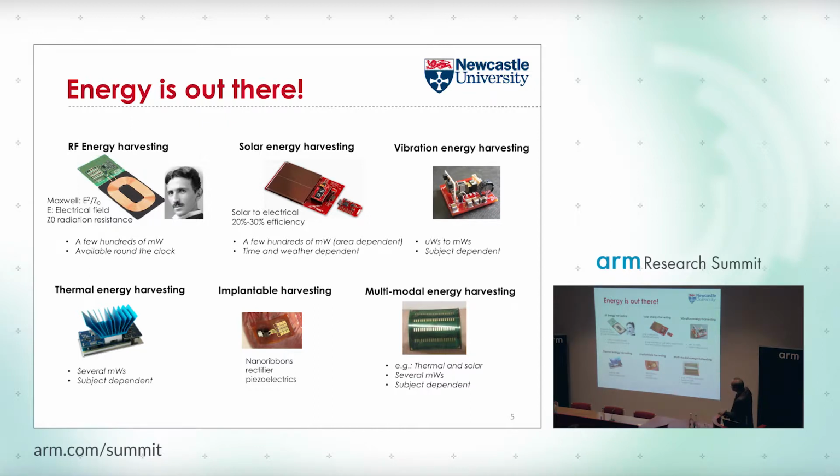Then we have some newer trends of thermal energy harvesting, or even implantable harvesting. You implant some piezoelectric devices alongside, for example, implanted heart pumps and stuff like that, so you can scavenge energy from that as well. You also have multimodal energy scavenging, where you can have thermal and solar energy scavenged at the same time. You can pretty much fix that on top of your hand. And again, depending on the environment and also the subject, you could scavenge several milliwatts of energy.